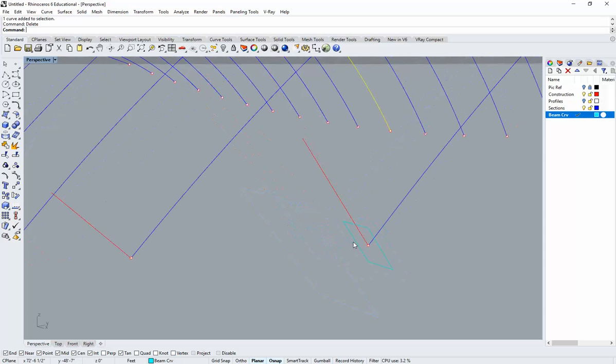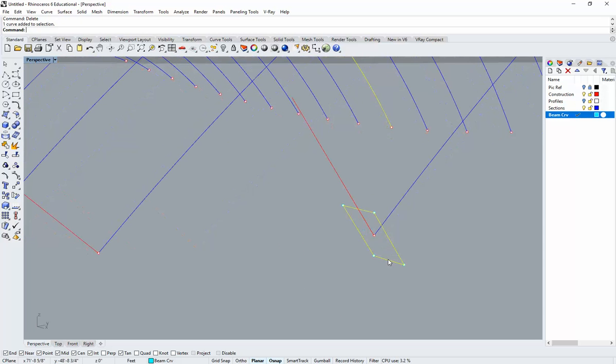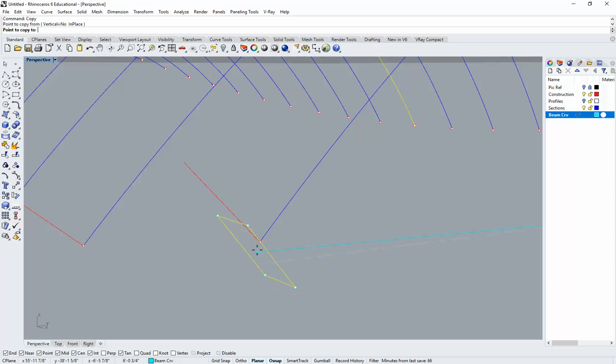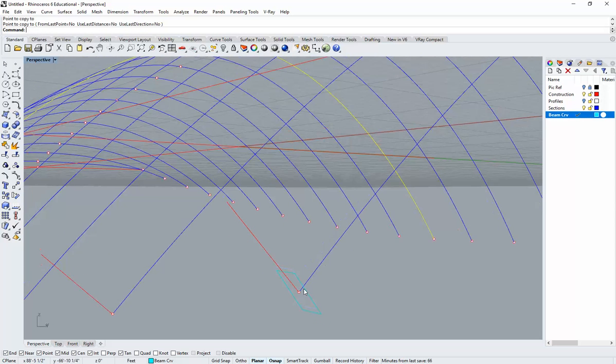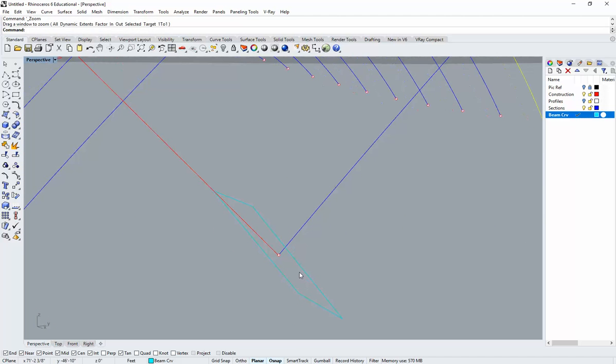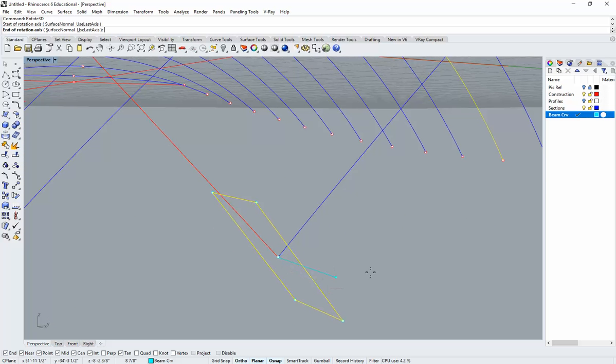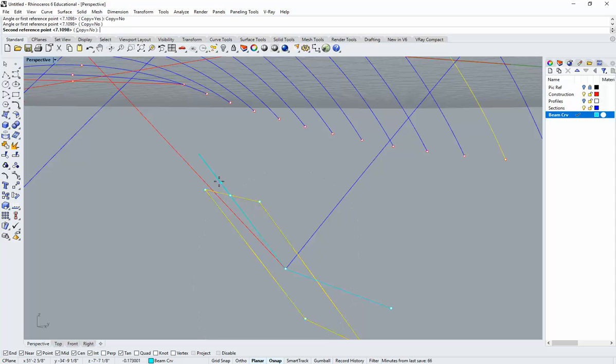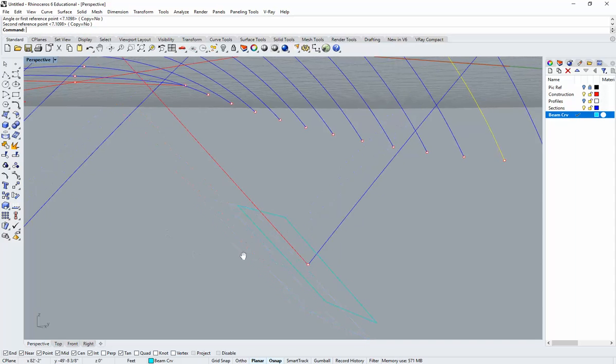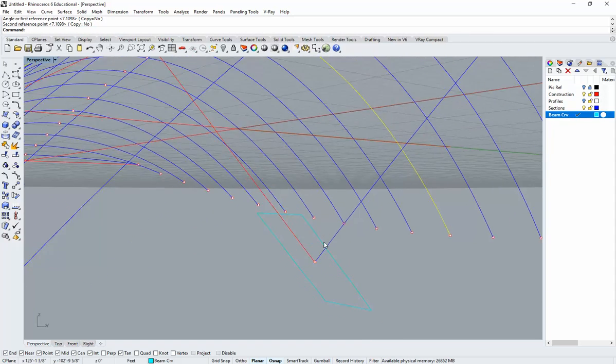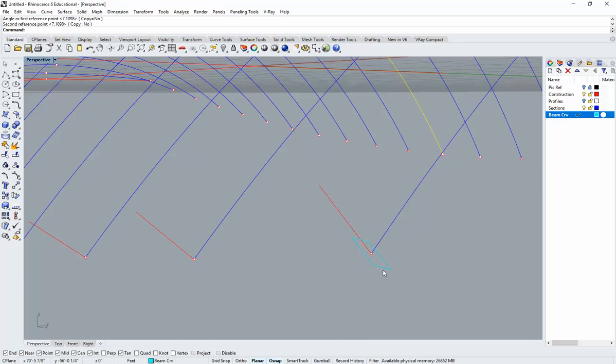Let's do that one more time, and this time I'm going to turn copy off. So let's make a copy of this first, pop it over here, zoom in a bit, run my rotate 3D command again. Click. After I set my axis, I can then go up to the command line and turn the copy off because that's unnecessary. Click my midpoint, set it to the red line, as you can see there. And so this would be the process that you can go through instead.